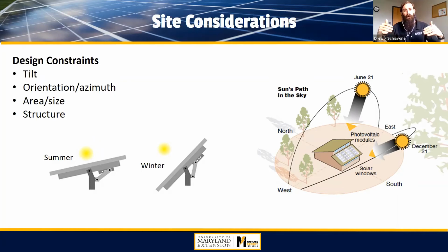You can have some deviation from that, especially when you consider a rooftop system. If you're putting a solar photovoltaic system on your roof, you're really kind of restricted to the slope of your roof. Yes, you could change the angle of your roof, but again, that's going to require additional material and supply to change the angle to match our 39 degrees that we're aiming for. So it's typically best if you're putting it on a roof, just take the lower efficiency and get the angle of your roof to the best you can.